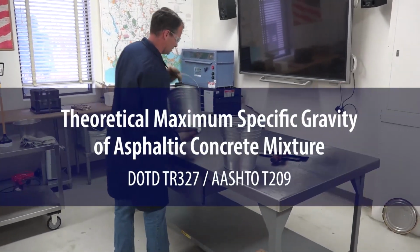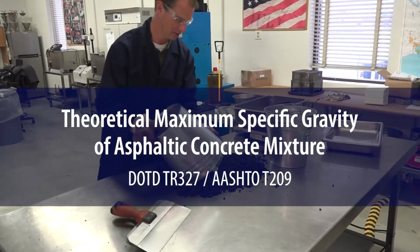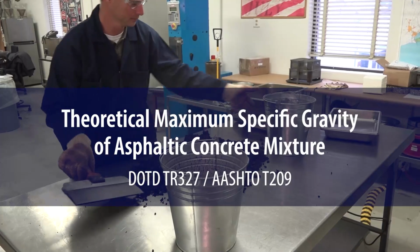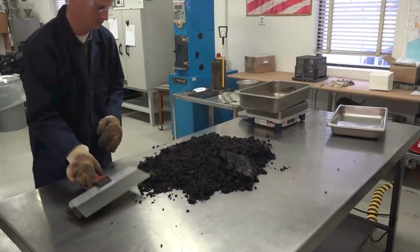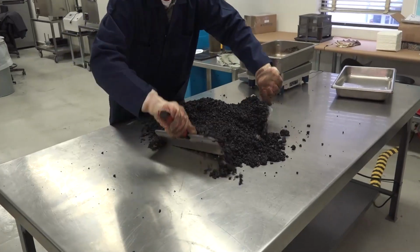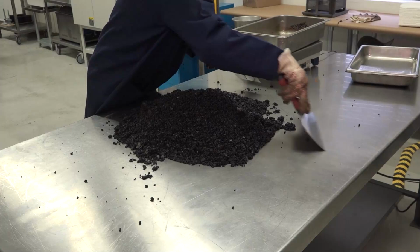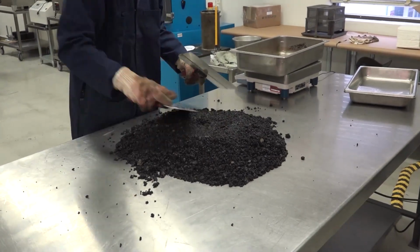DOTD designation TR327 and AASHTO T209, determining the theoretical maximum specific gravity and density of uncompacted asphalt mixtures at 25 degrees Celsius. The theoretical maximum specific gravity test, also known as GMM, is vital in determining the quality of asphalt mixtures. The GMM value is used in all subsequent calculations when determining volumetric properties.